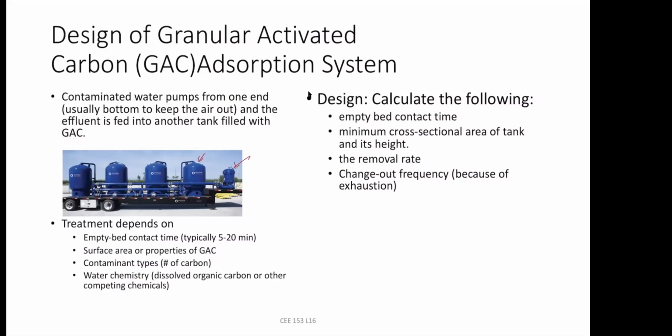So that means you have to think of the size, because that will determine how much activated carbon you can pack inside. It also determines the porosity. It's the same concept as retardation factor. More porosity, faster it's going to move through it, but it's not going to interact with the activated carbon. So you have to make the size smaller. So again, these are a couple of things you have to determine.